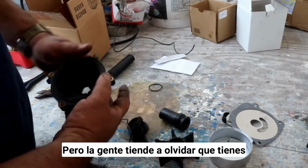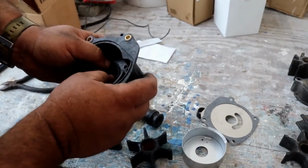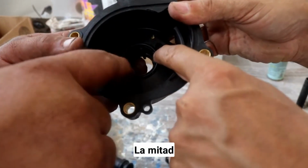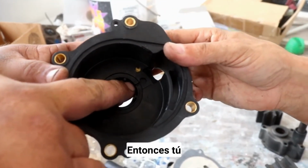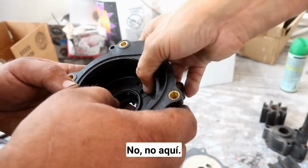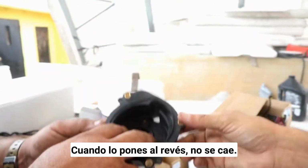But people tend to forget you have an O-ring that goes in here. What I do is put grease only on half, because if you look here, there's a weep hole. If you put grease in the weep hole, you'll cause an overheat. So you only put grease down here. The only reason I put that grease is so when you flip it upside down, it doesn't fall.